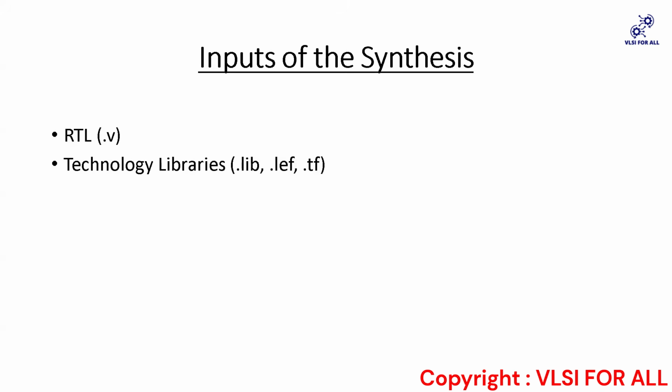Coming to the technology file, it contains the physical properties of the fabrication process. It contains information like resistance, capacitance, design rules, width, spacing. So the technology file is compatible with both the .lib as well as the .lef file.